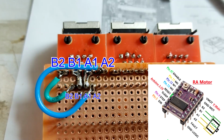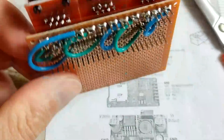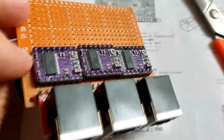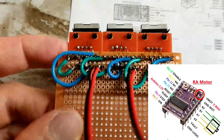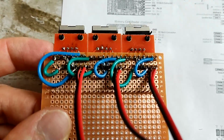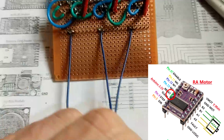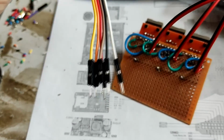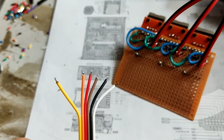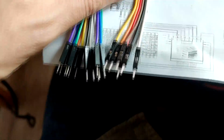So here we have the 4 wires of the motors coming into the 4 entries of the drivers, and do the same for the 2 other drivers. Then I soldered a black wire for the ground and a red wire for the VMOT to supply the motors. Then I bridged the sleep and the reset pins of the driver with a blue wire for the 3.3 volt supply. Then I took some 30 cm DuPont wires and I cut the end to connect the other pins of the drivers. I made 3 like this for the 3 drivers.